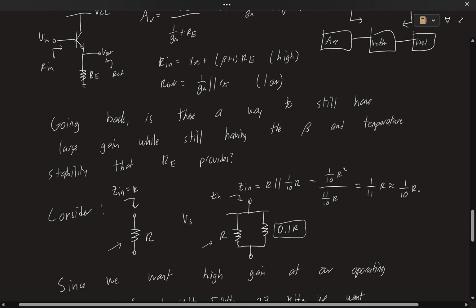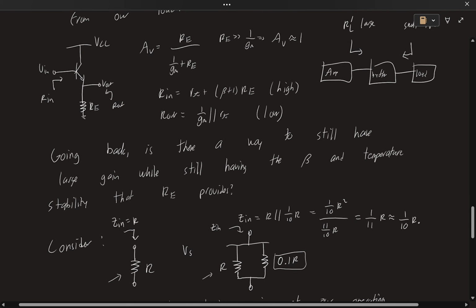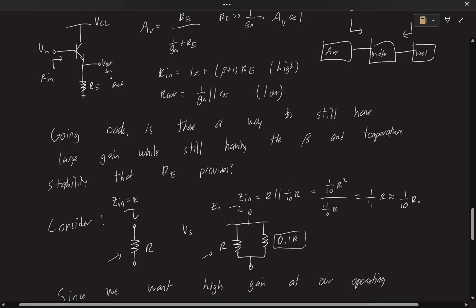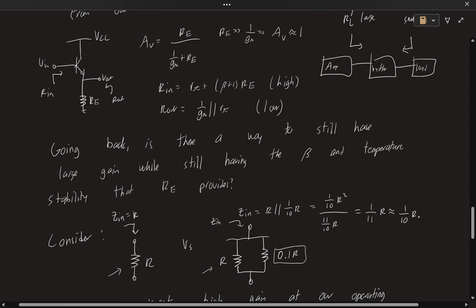Okay, so that being said, in RF, we operate at different frequencies, right? We want to amplify a 1 megahertz signal at some points, we want to amplify 5 megahertz. Then right before we send it out to an antenna, we want to amplify our 27 megahertz, right? So we want high gains at these frequencies, and ideally, we want a lower gain at other frequencies. In other words, we want the maximum gain at this frequency, right?